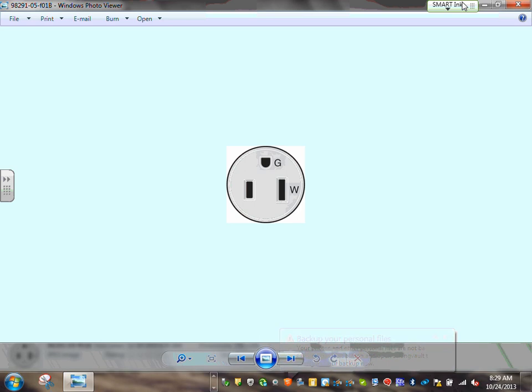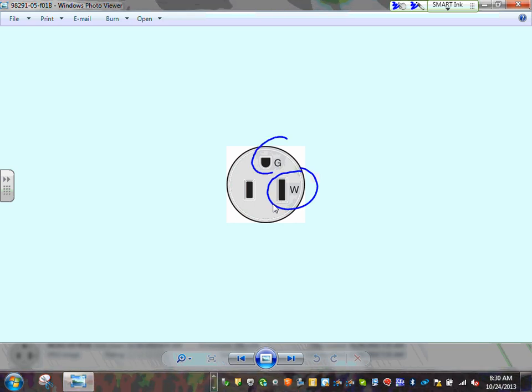So the rest of it is just a couple of pictures, guys. Here's the slot that says white. This is my white, of course, for the grounding conductor. That's your green for the equipment ground conductor, and that's your hot for the ungrounded conductor. This is the configuration that NEMA came up with, guys, for a 15 amp 120.